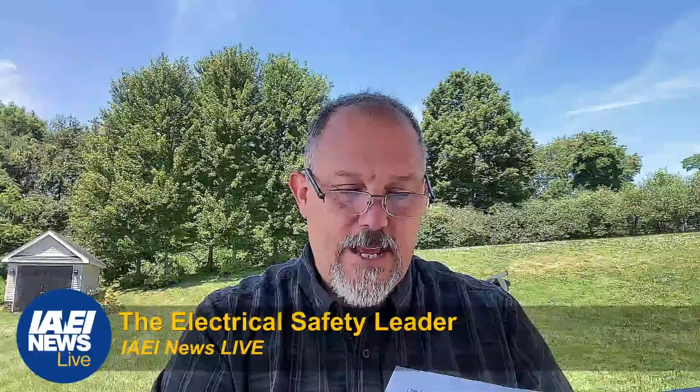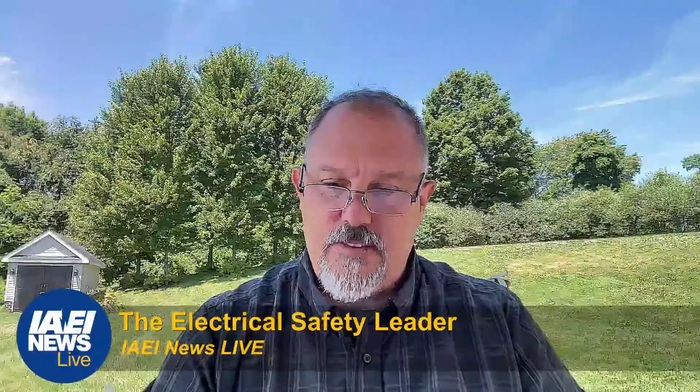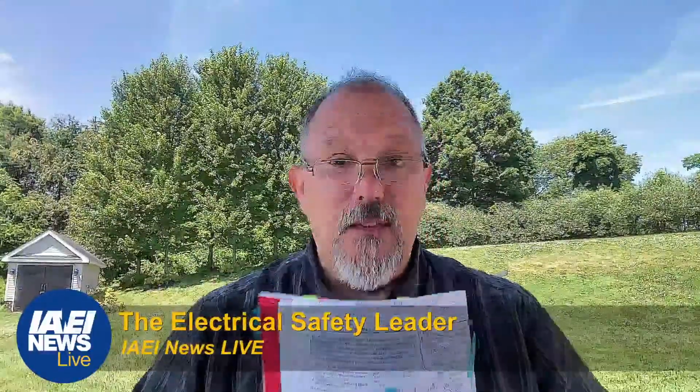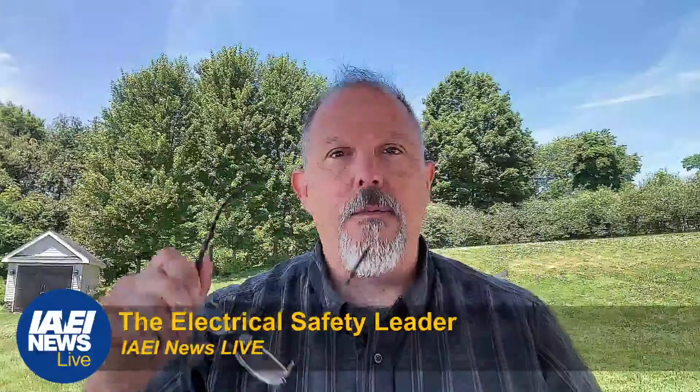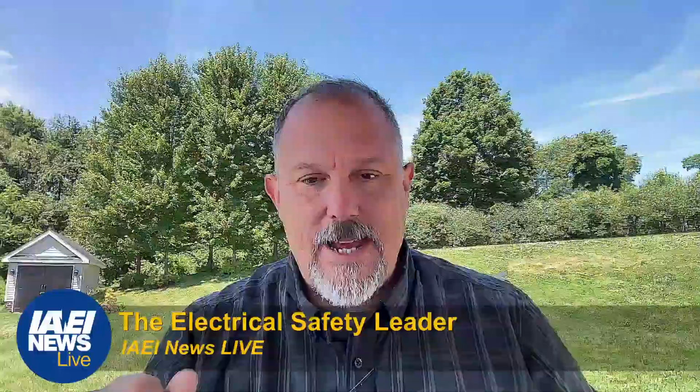Okay, and then in 120.3 they talk lockout tagout equipment, lockout tagout procedures. Okay, they've got simple and complex. There are so many. Then there's the process for establishing and verifying an electrically safe work condition. So Article 120 is the article that you're going to be living in if you want to really understand NFPA 70E's take on lockout tagout.